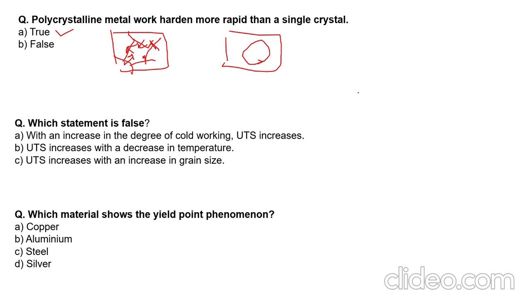If I talk about grain boundary pinning, for example, if you have this large structure and, say, I'm showing two crystals here. There is always some point from where the dislocations originate. So dislocations are originating in this grain and in this grain also, and these dislocations are approaching the grain boundary.